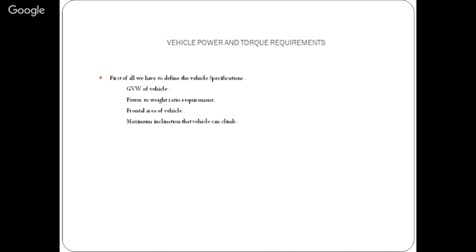And then the maximum inclination that the vehicle can climb. As a government rule to design the roads, the maximum inclination in the roads is up to 7 degrees. But in drastic conditions, for example, in mining application, in tractor application, other applications which are not specialized or standardized, we have to increase that gradability.